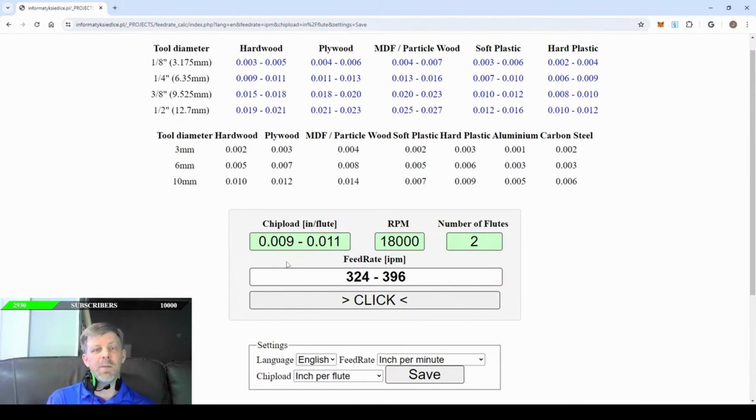Taper ball nose bits have a really long cutting surface. They're designed to cut deep. And because in a finishing pass in 3D, the wood left over from the roughing passes is very minimal, in this situation you can run your plunge the same speed as your feed rate. So if you have a 120 inch a minute feed rate, you can run a 120 inch a minute plunge at the same time. And that's generally with the taper ball nose bits and finishing passes in 3D when you're cutting very little material.